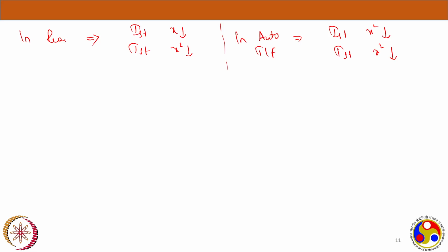See, this method is only applicable if your motor is designed for a delta connected winding for normal operation. I mean, during normal operation your winding should be in delta, because at the starting only we are making it a star. Once it picks up, we will again switch it back to the delta. For normal operation, your motor is designed to be connected for a delta based winding only.